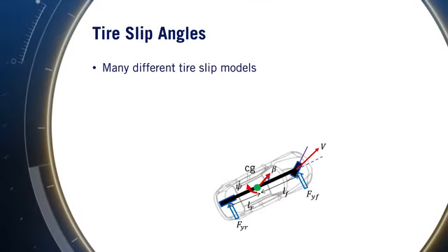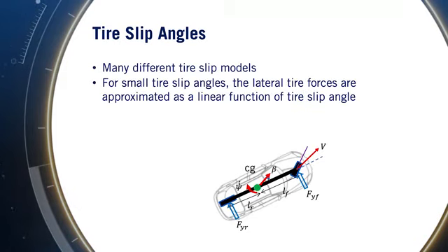One of the most important components in vehicle dynamics modeling are the tires. Tire forces are generally hard to predict exactly, and tire models tend to be nonlinear and empirically identified. We'll explore some of the more common tire models in detail in the final video in this module. Fortunately, however, for normal driving conditions, a simple linear approximation can be used to model tire force generation.